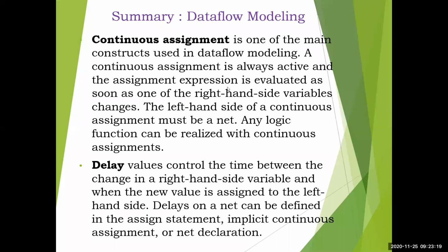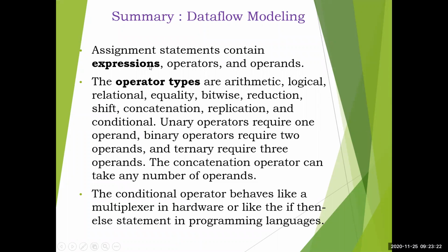Then we introduced expressions. Assignment statements contain expressions, operators, and operands, and we went through the various operator types in detail. The operator types are arithmetic, logical, relational, equality, bitwise, reduction, shift, concatenation, replication, and conditional. This is a very big class of operators in data flow modeling, and this knowledge is necessary for modeling any circuit at data flow level.